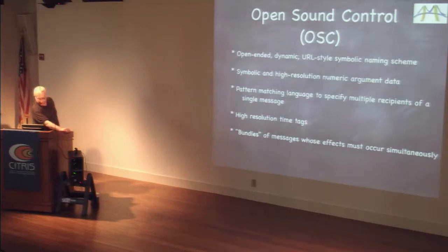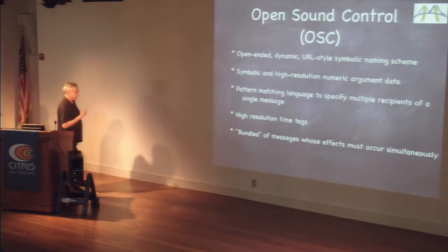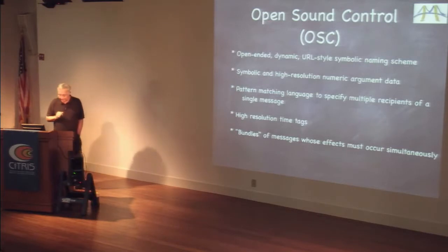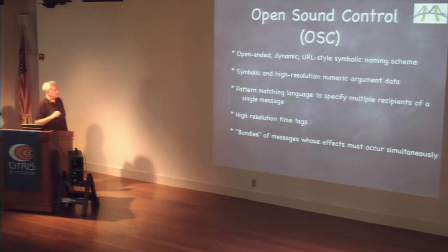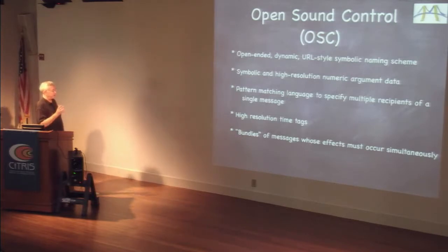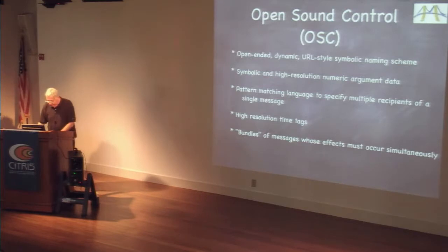I won't be able to go into that very much, but the important feature is that this is a messaging system that we can send control data with. It's got a pattern matching language in it, and, really important, it has high-resolution time tags, which are based on the IEEE 1588 specification, which is also the specification for time in the AVB protocol.